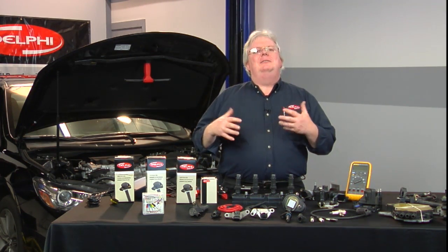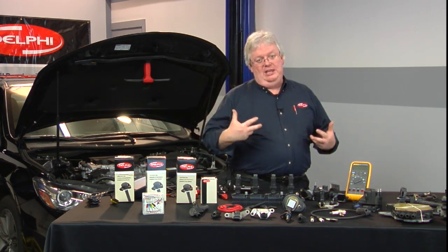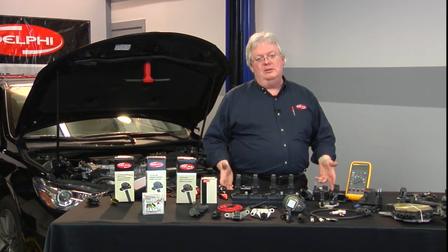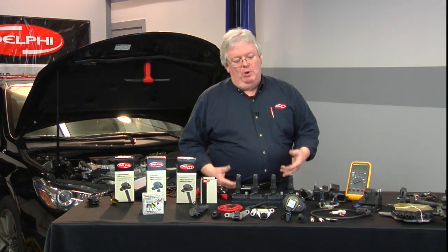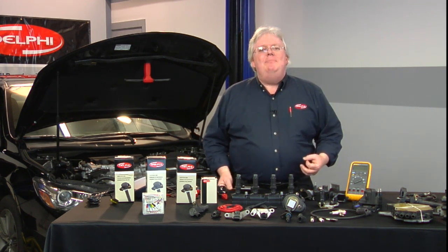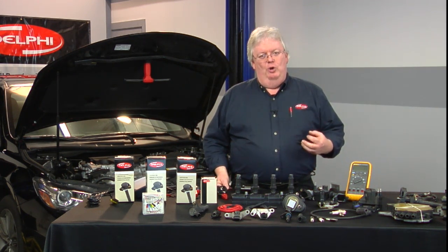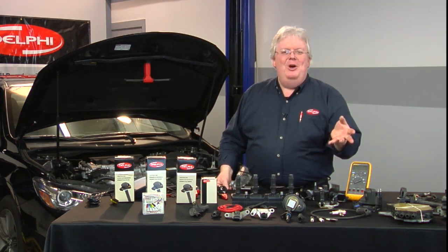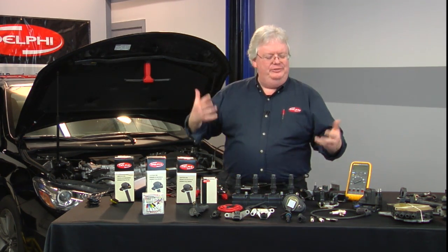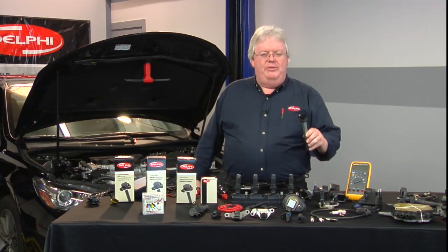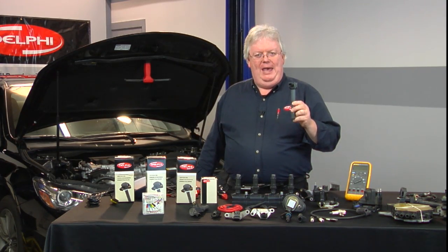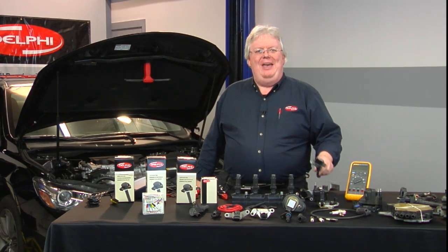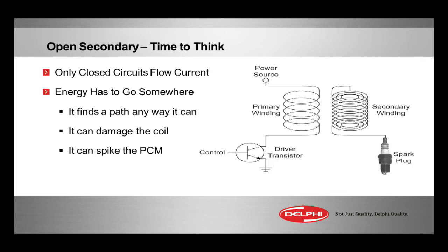Now, let's talk about some things that could cause us to think about what makes Coil-On-Plug modules go bad. What makes C.O.P.s go bad? Well, the same thing that makes any coil go bad, whether it be an old 62 Chevy Tower oil-filled coil or a brand new 2016 Chevy with a 3-wire smart coil go bad. Open secondary, that can cause coil damage, it can cause module damage.